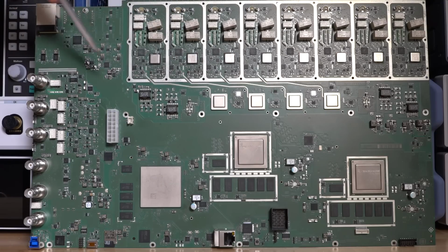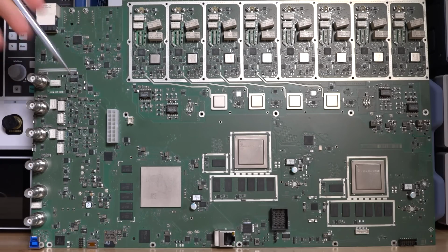There's a really cool analog front end, which we'll take a look at closely as well, and all the reference in, reference out, arbitrary function generators are also contained on this board. All the power management is also here. It's amazing that you can make all of this work. I'm not sure what the yield of a board like this is, but there is a lot going on in it. And even the Ethernet and the USB interface are also all shared in here. I'll flip it to the other side so you can see the other side too, but we do have to take a close look at the architecture in a second.